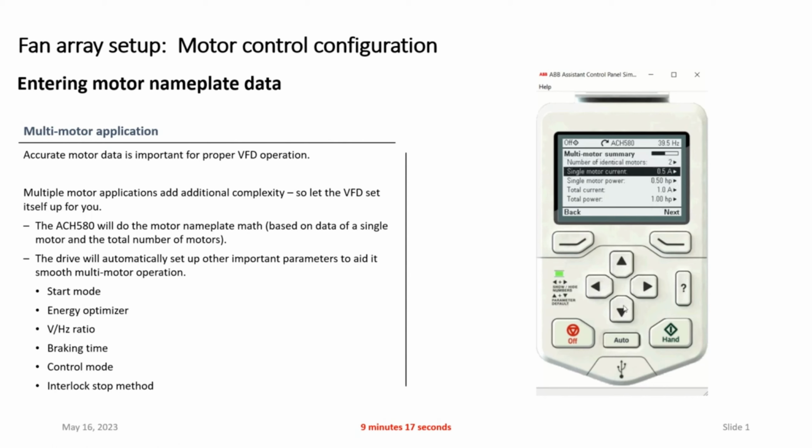If I wanted to, I could come in here and change any of these values if I realize I fat-fingered something. So if I realize those motors are really 0.4 amps as an example, or 0.6 amps, I could go ahead and change that. You can see it updated my 0.6. Now I really have 1.2 amps total. So I've got my motor data in there correctly.